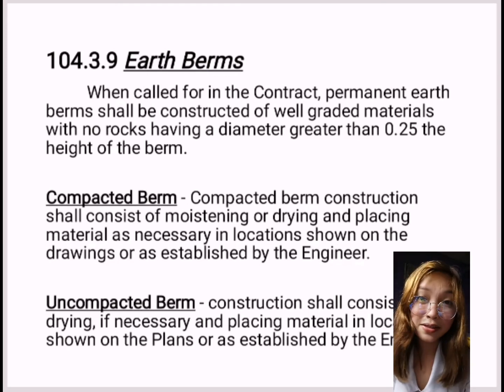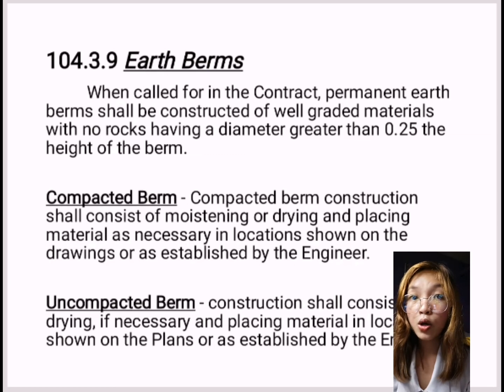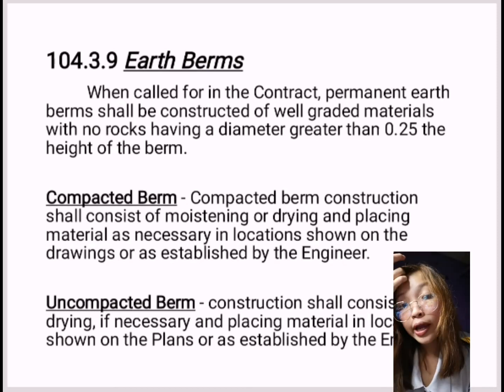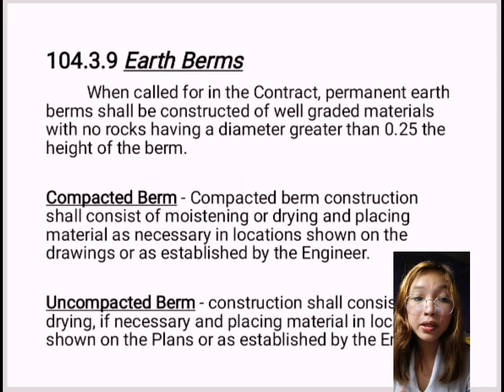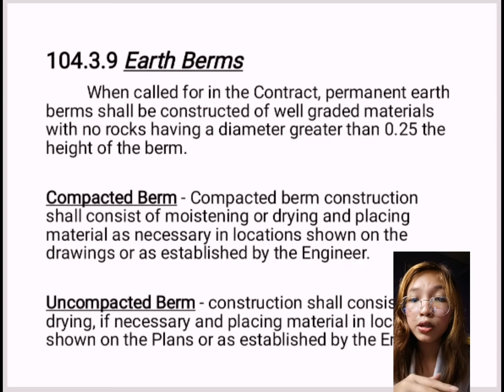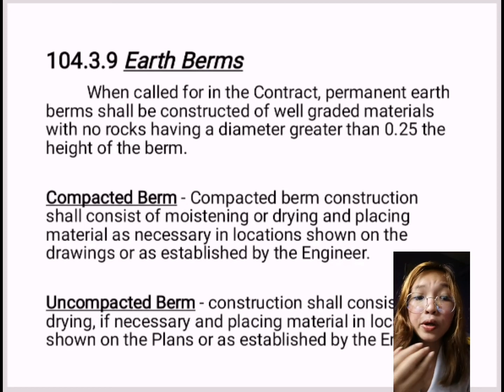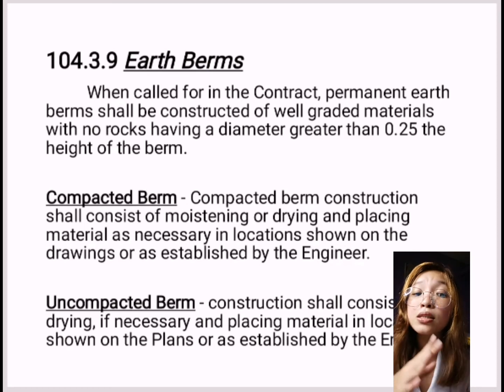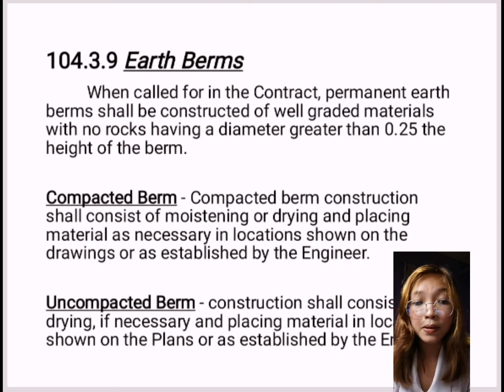So next is the uncompacted berm. If we have compacted berm, we also have this uncompacted berm. Construction shall consist of drying if necessary and placing material in locations shown on the plans or as established by the engineer. So material shall contain no frozen material, roots, sod, or other deleterious material. So contractor shall take precautions to prevent material from escaping over the embankment slope.